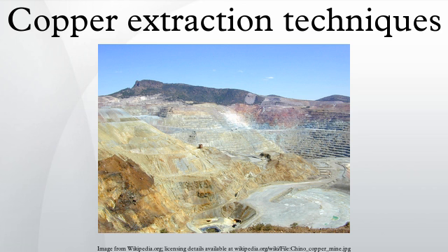The greater the iron content of the feed, the more iron that will need to be rejected to the slag for a given matte grade. Similarly, increasing the target matte grade requires the rejection of more iron and an increase in the slag volume. Thus, the two factors that most affect the loss of copper to slag in the smelting stage are matte grade and mass of slag. This means that there is a practical limit on how high the matte grade can be if the loss of copper to slag is to be minimized.